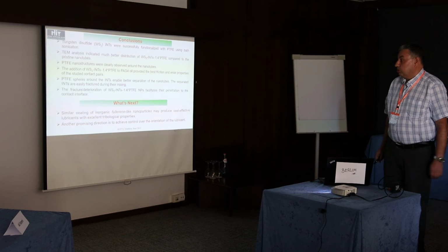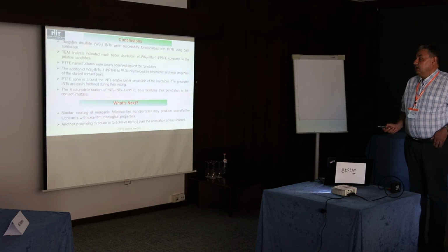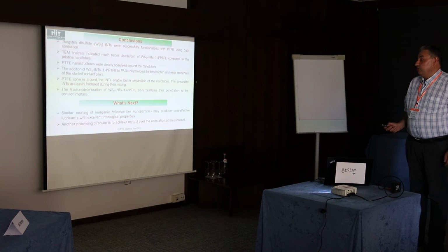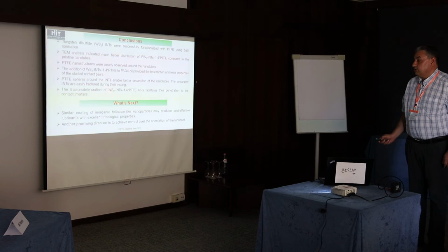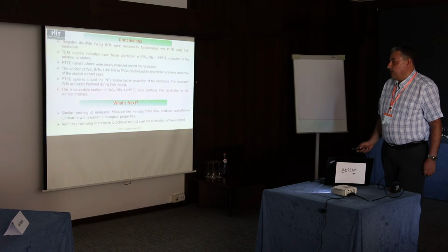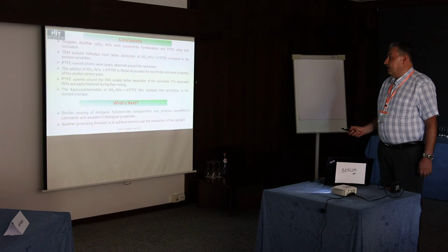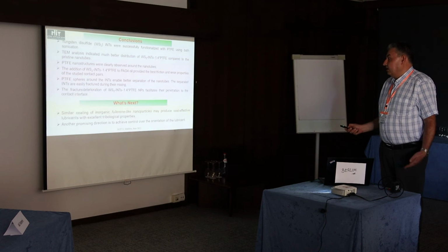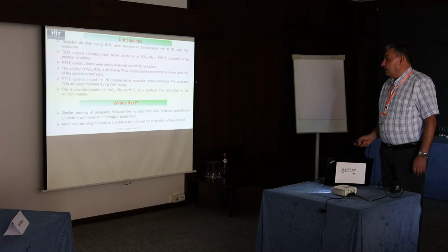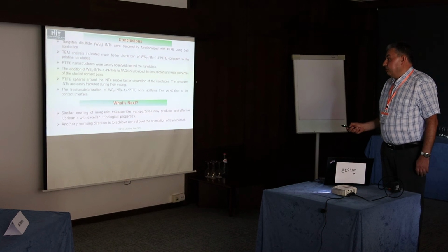So now I come to conclusions. Tungsten disulfide WS2 nanotubes were successfully functionalized with Teflon using bath sonication. Our analysis by TEM indicated much better distribution, less agglomeration of Teflon-covered WS2 as compared to pure nanotubes, and the Teflon was clearly absorbed around the nanotubes.